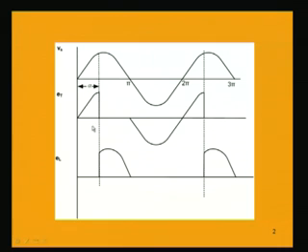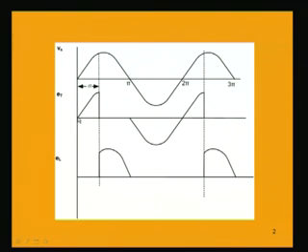the voltage across the thyristor becomes 0, because that we have assumed in comparison with the voltage at the input. We can assume that the thyristor is having a voltage drop of 0, because the voltage drop is very small and it can be neglected. So, once it is on or in conduction, the thyristor will be having a voltage of 0 across it. Up to the point of conduction, the thyristor is not firing.